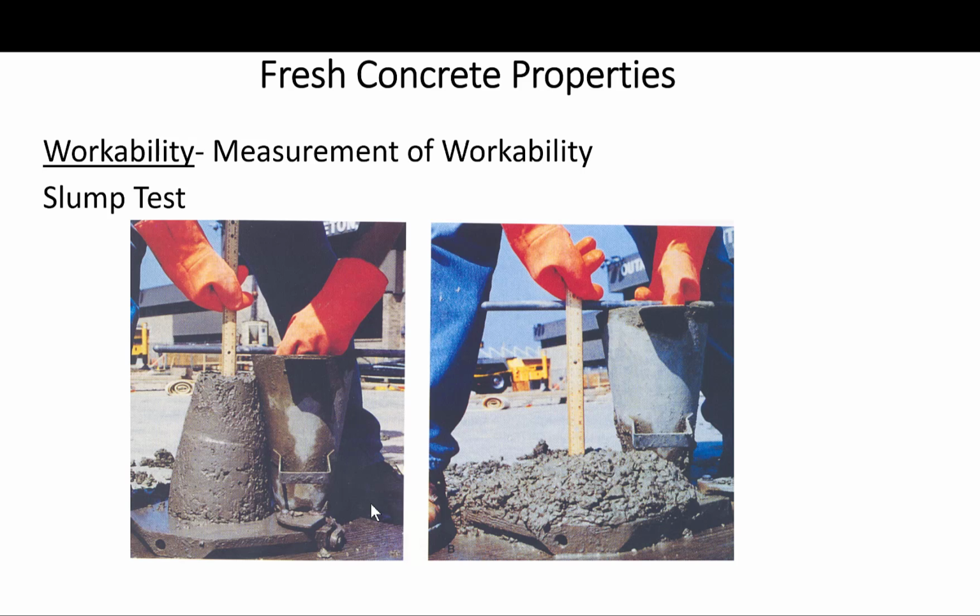Stability, which is the ability for concrete to remain a stable, coherent, homogeneous mass during handling and vibration without the constituents segregating. So basically, that's what the test for workability should at least contain within its parameters to measure.